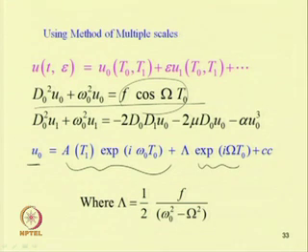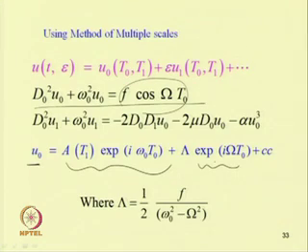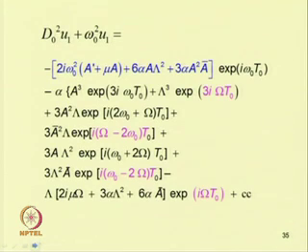So, in case of hard excitation, the response u0 can be written in this form. Now, substituting this in the second equation, we can see there are several resonance conditions available in the system, or several terms that will lead to an unbounded solution. So, one has to study what the conditions are for which the system response becomes unbounded.